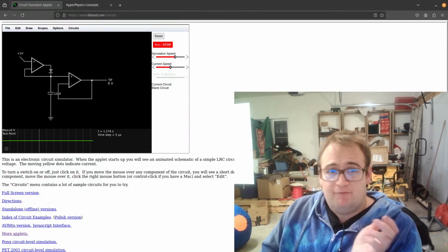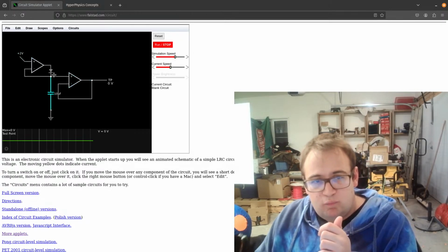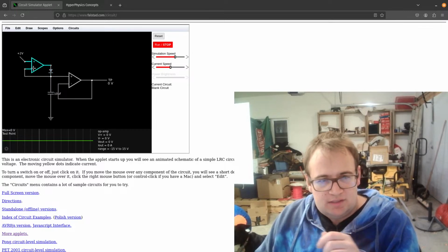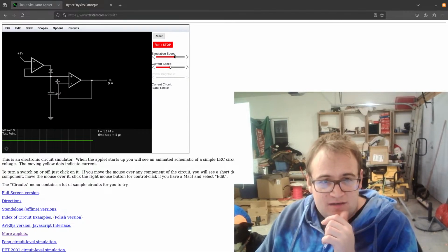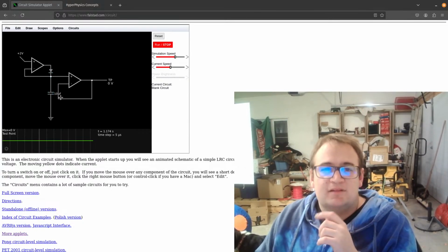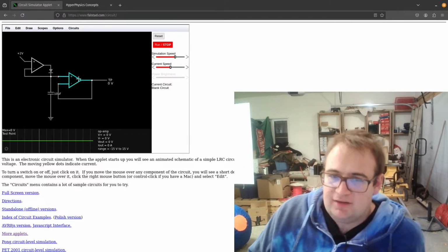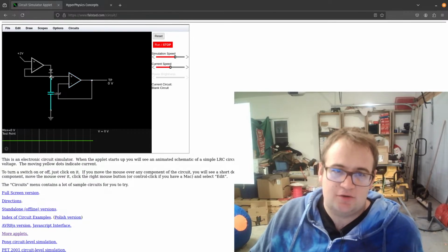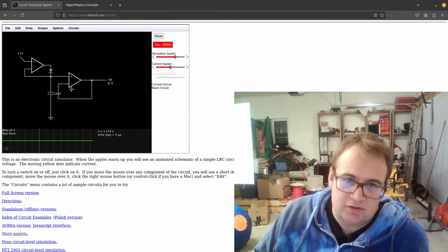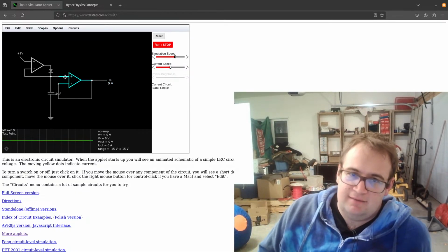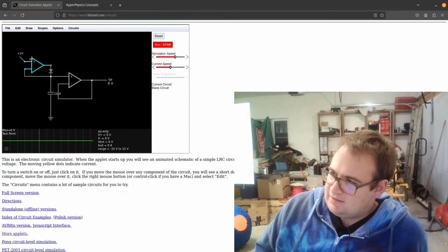And then if we took this away, well, actually, this won't change in voltage. It's not going to backflow or anything, because we have this diode here and this capacitor here holding the output there. So what it does effectively is, when this rises up to 2 volts, then this will also go to 2 volts and it will stay there. Yeah, does that make sense?